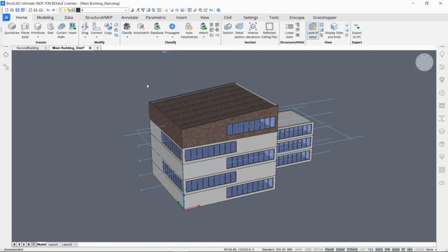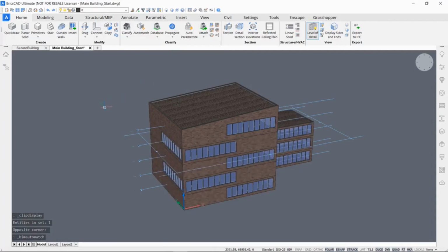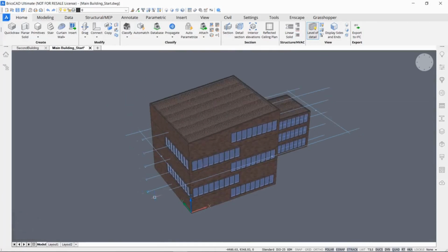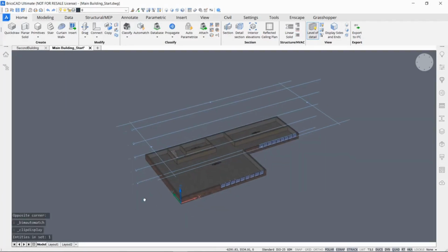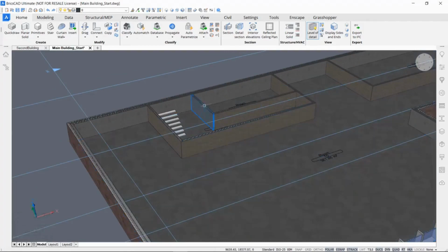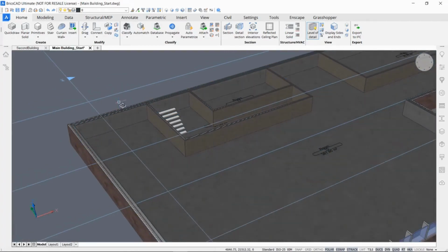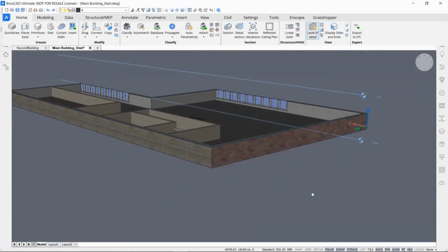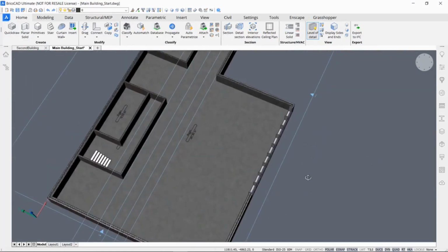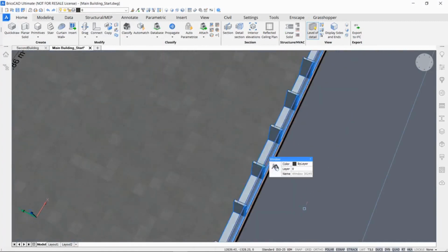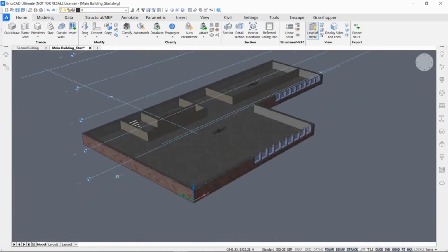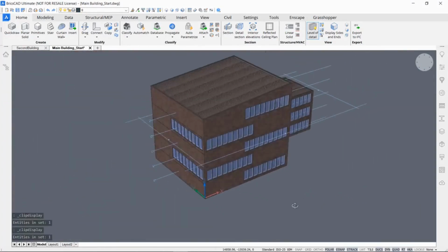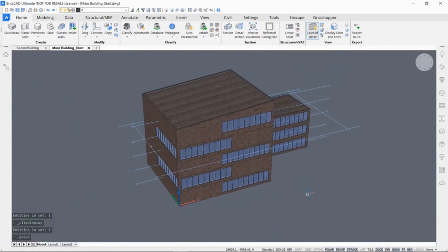So let it run BIM Auto-Match, and you will see it has auto-completed our entire building to the compositions and the parameters that we wanted. So let's click on another floor section and open it. And you can see here all the interior walls has the same composition. Also the back wall has a different composition from the front walls. And lastly, of course, also the window parameters, the frame depth also has been changed. So that looks good. If I close that back again and save this file,